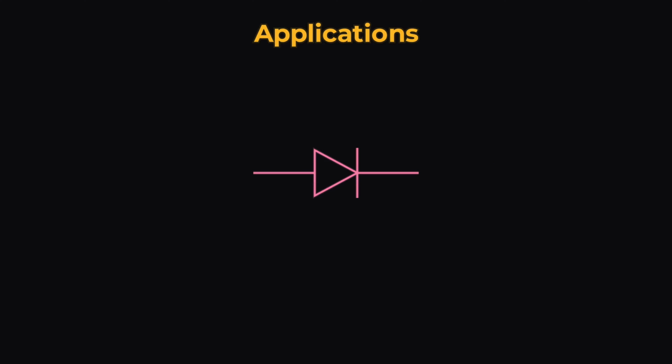The second job is light emission. A forward-biased junction drives electrons and holes together, and recombination releases the energy as light. The photon energy is roughly equal to the bandgap, so the material sets the color of the LED.